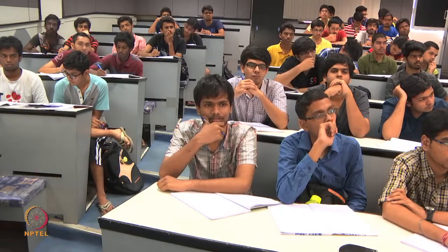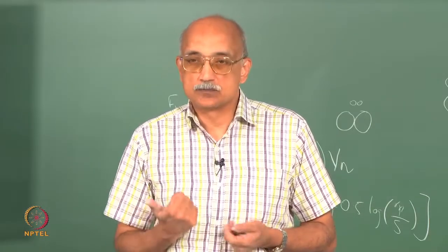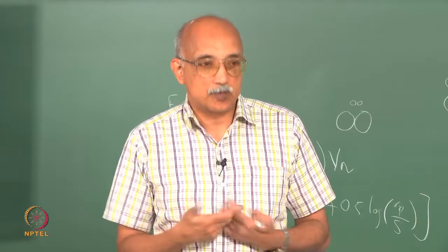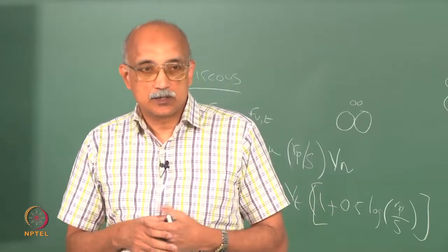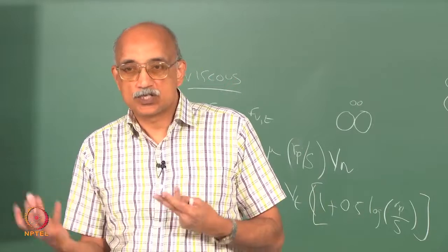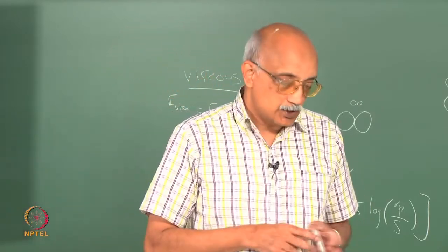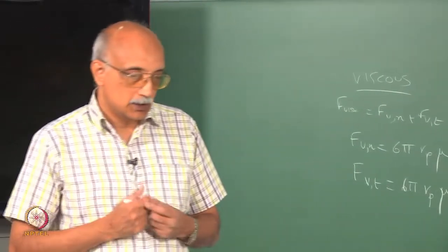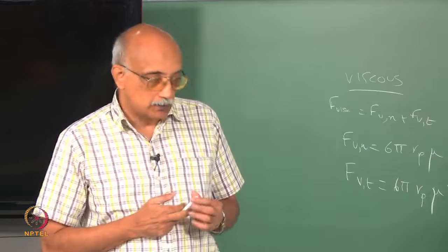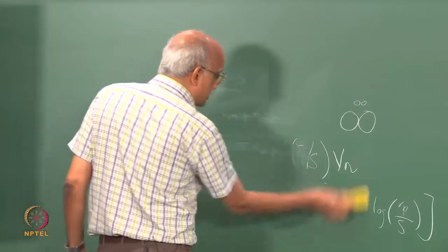There are two parameters that can give you some very good indications. The first is number of particles. If cohesion is happening, the number of particles will decrease, right? The second related parameter then would be mean size. If cohesion happens, the mean size will keep increasing. So, in order to assess the stability of a particle suspension in any processing industry, the two parameters that people track very closely are the count of particles and the mean size of particles.